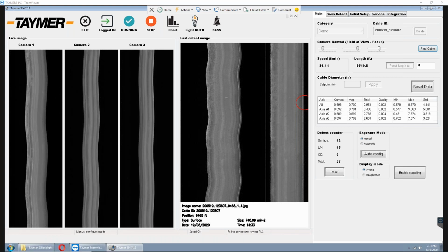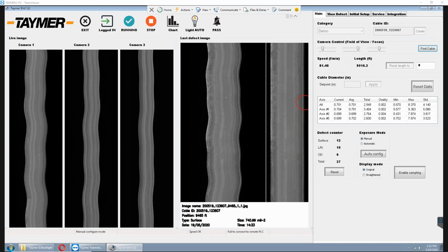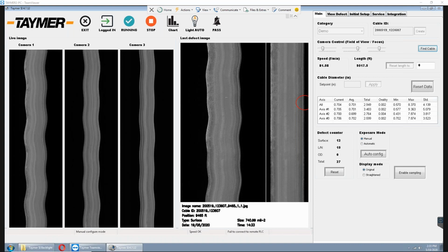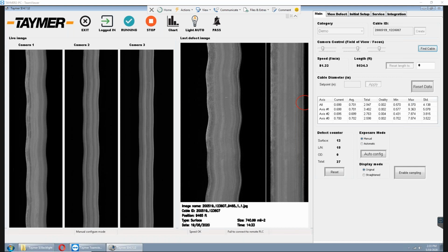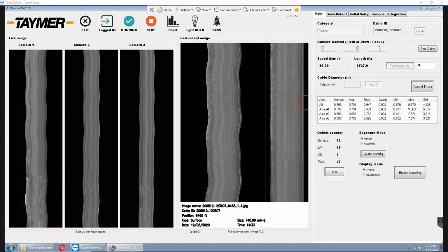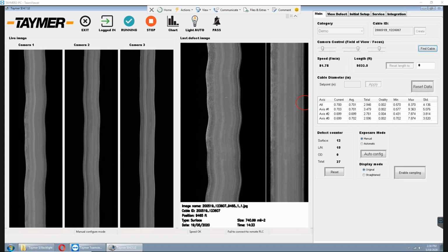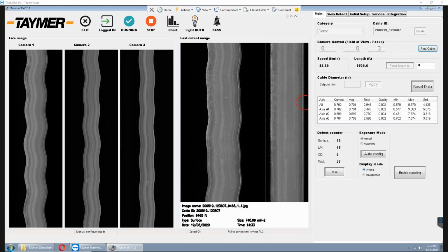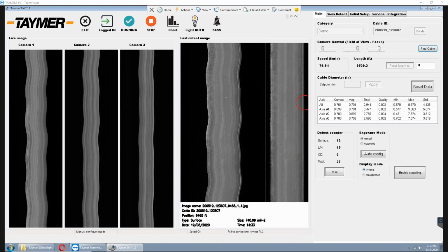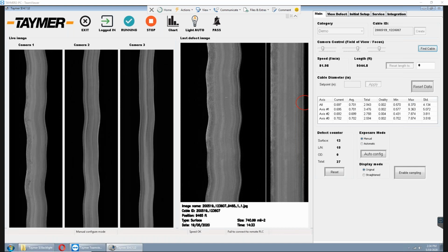Yeah. Hey, can you hear me? Yep. I'll talk through this one. So we have 3 single conductors that we would cable or twist into a single three conductor cable. And so identifying if one of those conductors is further away from center line than the others, prior to putting it through an extrusion process to cover it with insulated material.